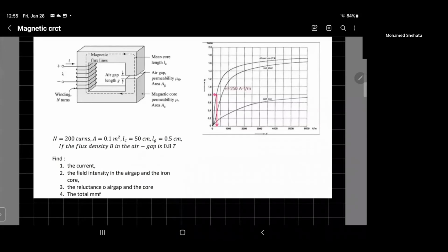If it's big, there is something I'm going to explain for why you find the magnetic field be like circles around. I want to keep it the same, going through the air gap, no disturbance in that. They call it fringing, coming out and making it like a bubble. We don't want this because it will make our calculation complicated. So let's assume it's very small.